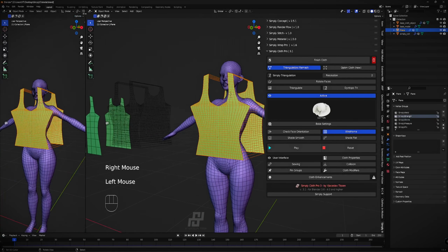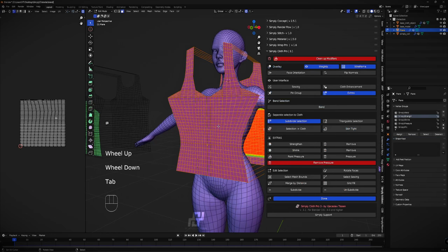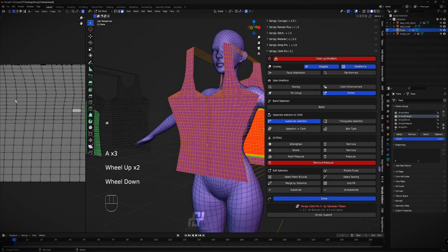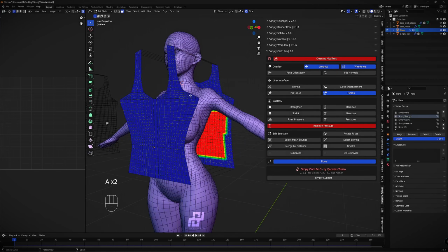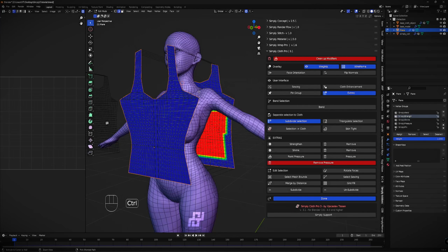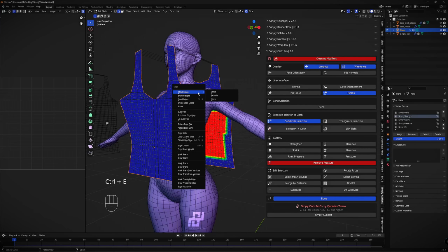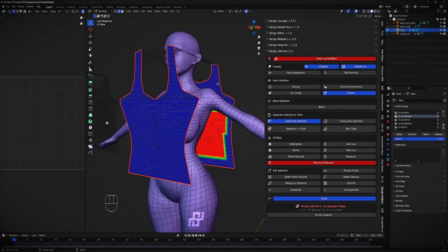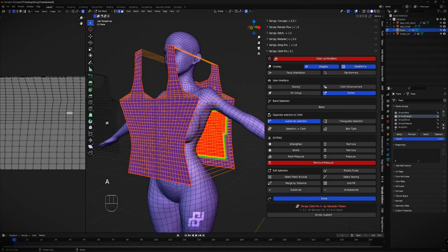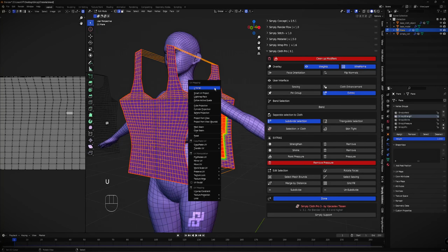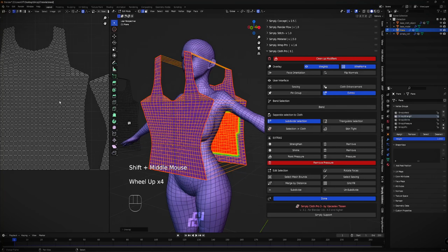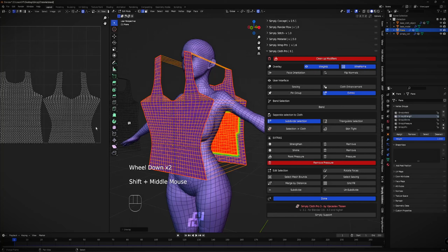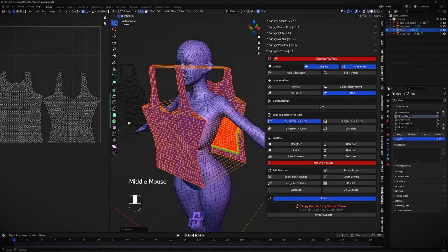We just make UV sewing lines. So if we have here, you see, what is this? It's not nice. I recommend an easy way here: select the mesh bounds like this, and then Control A and mark seams, and that's it. I select all, hit U and unwrap it. So we have here in our UV a clean object view of our cut and sewing patterns.